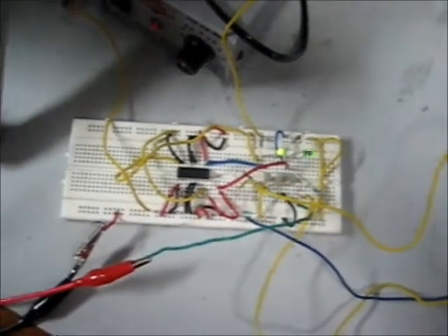The BeagleBoard produces a PWM which is fed to the board through the optocoupler and the motor driver. The duty cycle of the PWM is varied to change the speed and the degree of rotation of the motors depending on the nearness of the obstacle from the camera. The oscilloscope shows the output of the PWM.